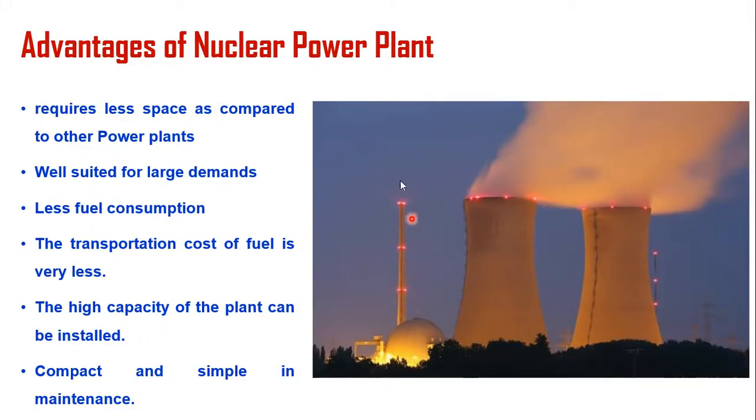And coming to the advantages of the nuclear power plant, when compared to the other plants, it requires very little space. Here there is no need for construction of any dam, unlike hydropower plants. And here there is no coal handling plant as in thermal power stations. Here only the reactor is enough. Only 1 kg of uranium will generate a large amount of energy. So a simple reactor is there. The remaining things are common.